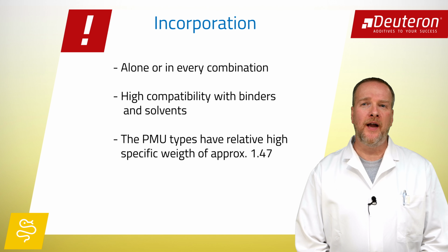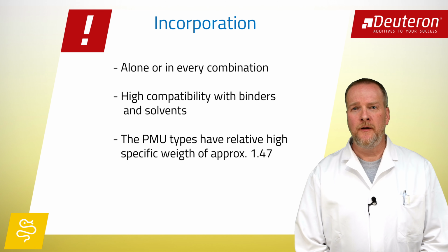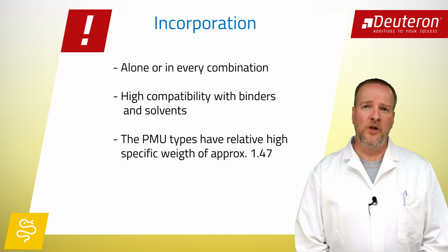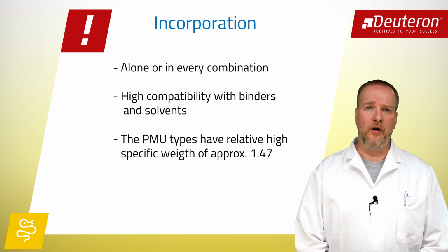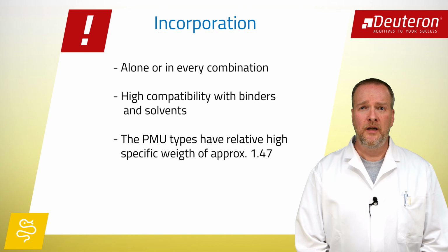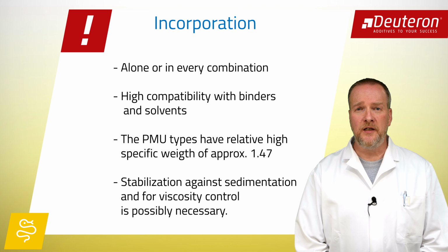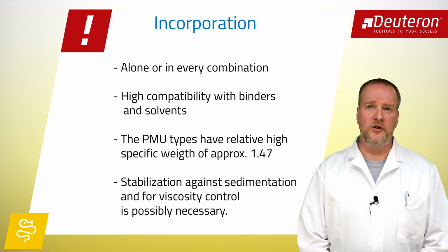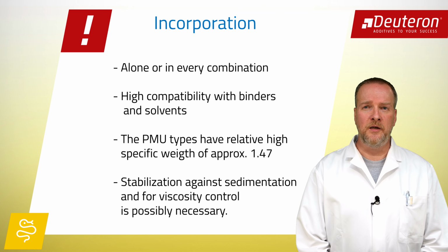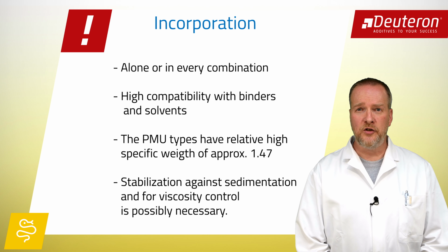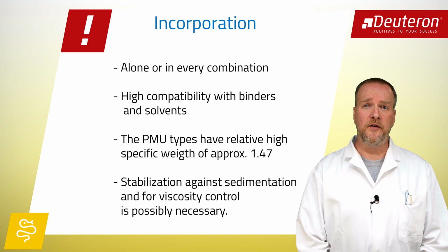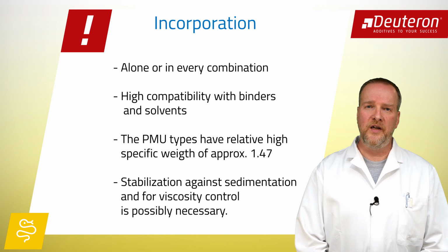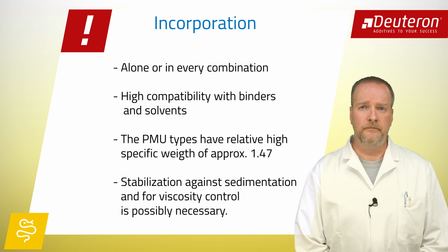Due to the relatively high specific weight of approximately 1.47, some formulations of low viscosity or unsuitable rheologic profile can tend to sedimentation of these additives. To avoid or reduce this, it's recommended to adjust the viscosity to a shear thinning behavior. Also, combinations with other solids can be advantageous to form no or easily stirrable soft sediment.